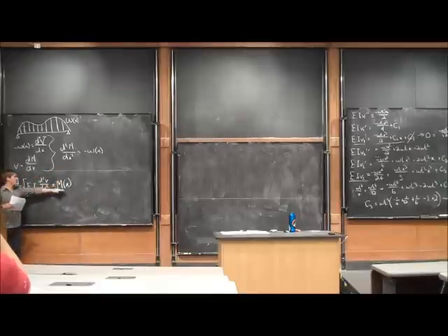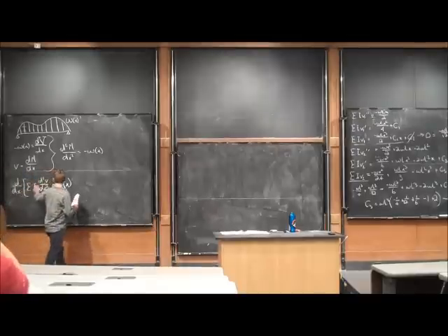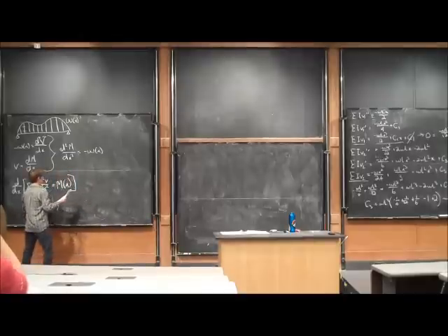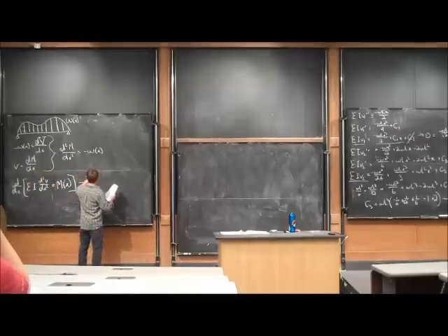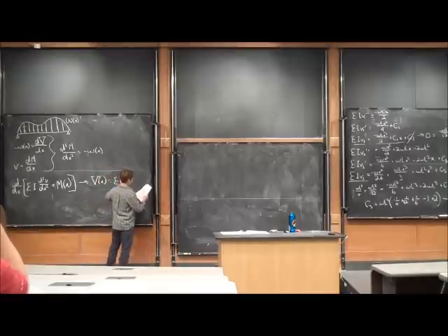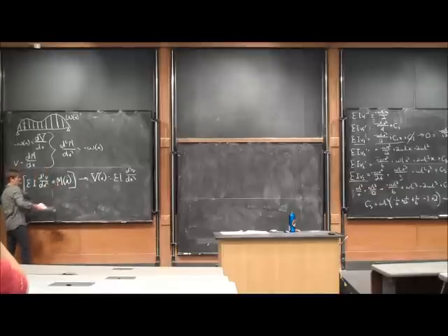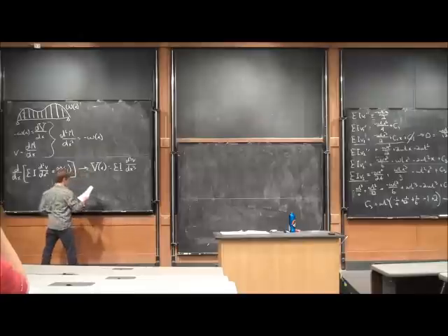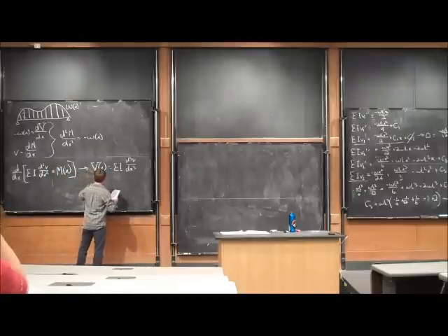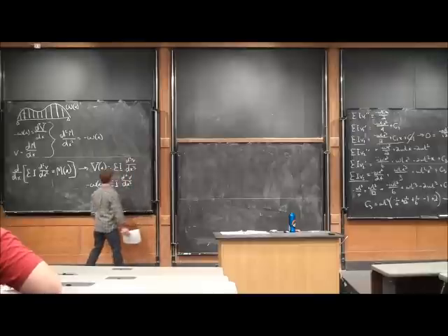We have that the moment function is equal to the second derivative of the deflection times E times I. We can take the derivative of this entire equation, and that's going to give us that the shear function is going to be equal to EI, the triple derivative of our deflection equation. We can then take the derivative of both sides of this equation, and we'll get that the negative of the loading function is going to be equal to E times I times the 4th derivative of our deflection equation.